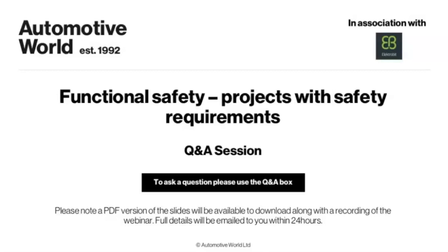This is a follow-up to the fail operational question. Can you run software on both ECUs to achieve an ASIL fail operational solution? Yes, you can execute them on both ECUs. Of course, you need to think about the diversity of your software, and how different you make your fail operational system. Maybe you choose different suppliers, maybe different application developers as well,